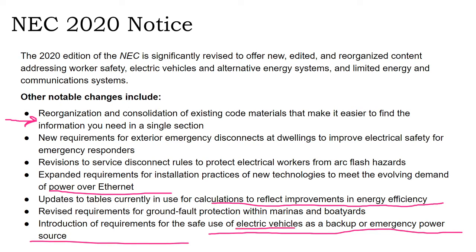I've been kind of looking at this in class for a while because one of the main differences between National Electric Code and International Building Code with regard to batteries is that International Code allows the use of electric vehicle batteries for building power. And so far, NEC has been ambiguous at best about it, saying that the batteries have to be listed for purpose.